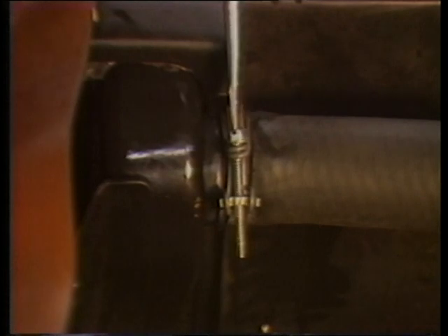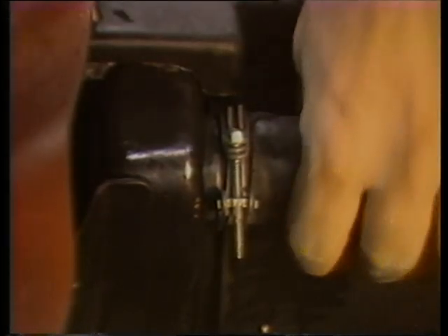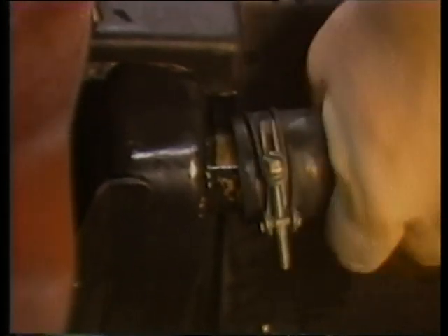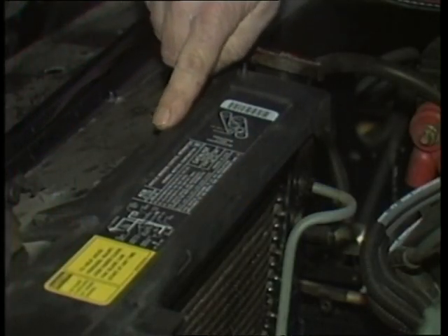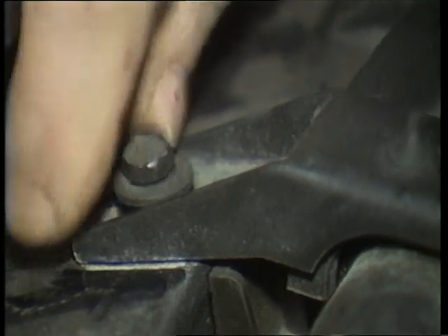To service a radiator, remove the top and bottom radiator hoses. Loosen the clamps and then pull while twisting on the hoses. Unbolt the cover or bracket that holds the radiator down into the vehicle, then unbolt the radiator shroud, which may be formed as part of the electric cooling fan mount.